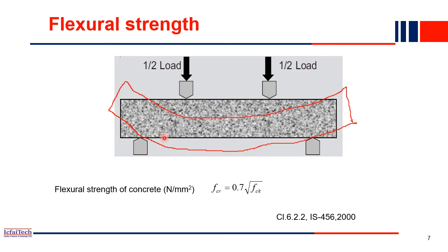So now after the beam bends, what will happen? At the bottom side, if you see, this portion is stretching, whereas the top fiber is basically compressing. See, these two fibers are coming nearby, right? Whereas this portion is actually stretching. So the bottom fiber length has increased, whereas the top fiber length has decreased. That's why the bottom fiber is having the tension force, it is stretching, whereas in the top fiber you will find compressive force acting, it is shrinking in nature, right?